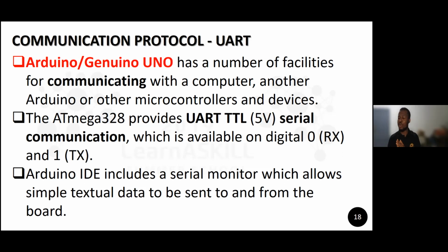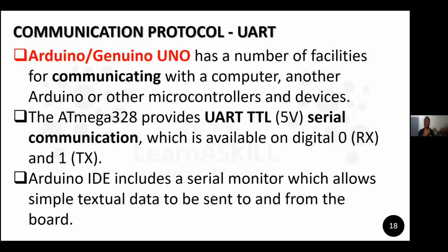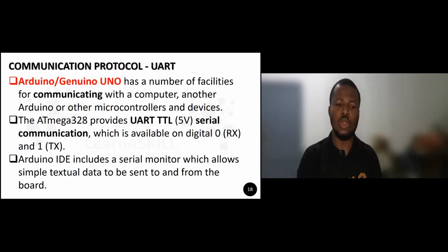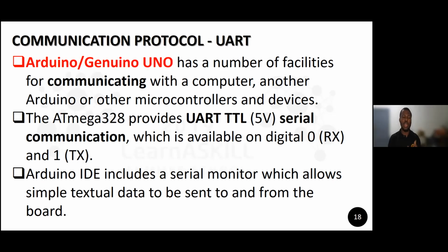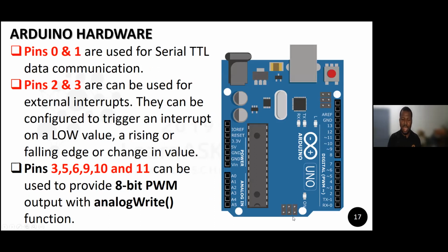I don't know whether that is okay for the one who asked the question. It is to avoid the conflict with the USB when you are loading a program. But of course, the USB is not the only means of loading code onto the Arduino. You can also use what we call the ICSP header. For those who don't know, this is the ICSP header. You can use it as a means of loading code onto your Arduino instead of the USB.